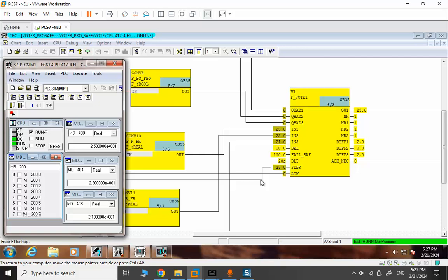So in the next case, we simulate the bad quality signals from the table, the second half of the table. If we have one signal, the Q bad is active, one transmitter 1 is not good. So the value will be between 21, 23, and 100. Still 23 is the median, and we are okay. We will work with that. If it's in the real application, we should go and check the transmitter, solve the problem, and return everything to the normal. So input 1 is not considered in the calculation, and input 2 and 3, the difference is within the deviation limit.